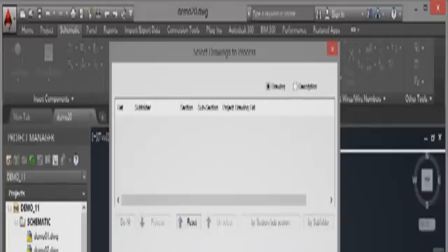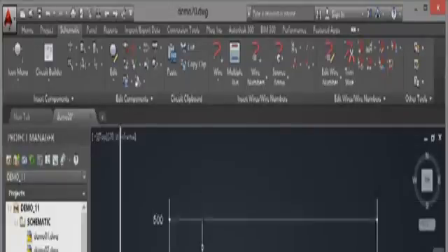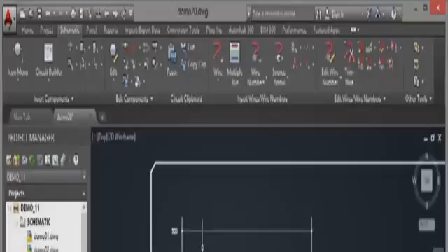Now, I know that there aren't that many ladders, so this shouldn't take too long. So what I do now is I just click on OK, and AutoCAD thinks about it. You can see it on the command line working through the drawings there, 3 of 14, 4 of 14, all the way through. And all it does is calculate those numbers. When I zoom in now, it starts at 500. So drawing Demo 20 is obviously the 5th drawing in that renumbering sequence. It just tidies up your numbering for you.